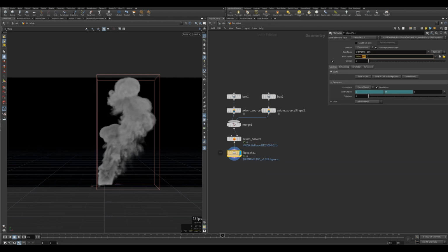All right. Generally, if it is a simulation, I'll put it in sim and then /$pip name, and then this one I'll just leave at your OS. Okay. So I'm going to change this to, let's say if you middle click on the base name here, you'll see it's file cache 1. So I'm going to change this to fire sim cache. So that base name changes here. All right, middle click again, it'll change back to $OS. All right, good.